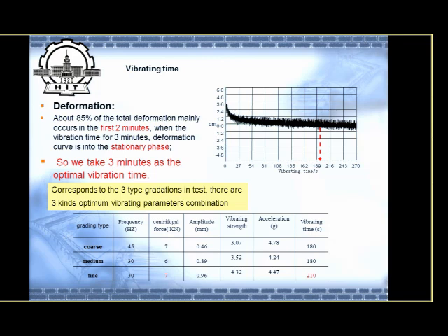We find about 85% of deformation occurs in the first 2 minutes, and after 3 minutes, deformation could go to a stationary state. So we take 3 minutes as the optimum vibration time.